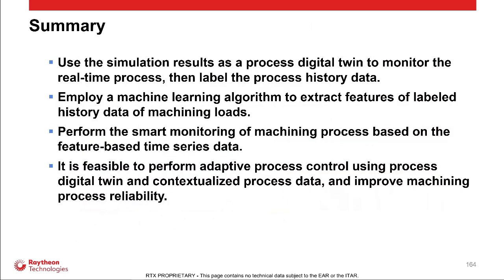So here is a summary. We use the physics-based model, considering the material removal together with the machine tool and its controller, then build the process digital twin and use that for real-time process monitoring and control.